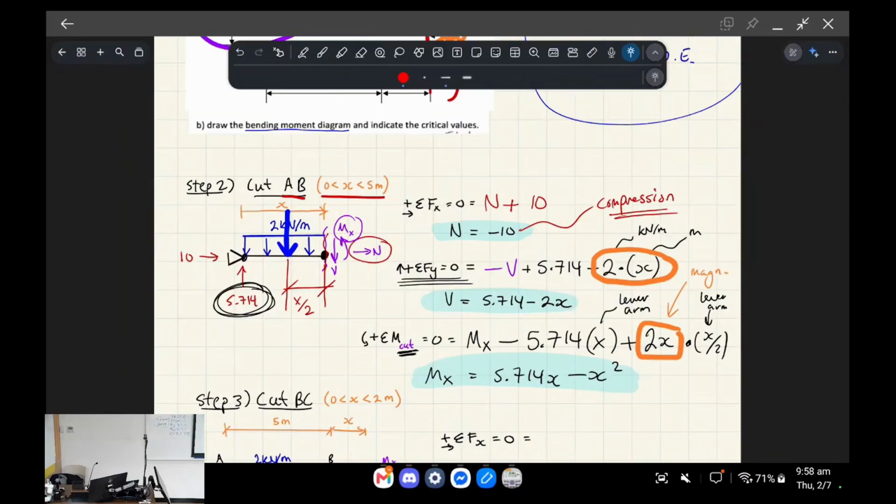I'm going to call this distance x, how far along the slice. There's going to be a counterbalancing force called V, the internal shear V, and also a counterbalancing moment, and then also an axial force, but in this scenario, that represents your internal force.